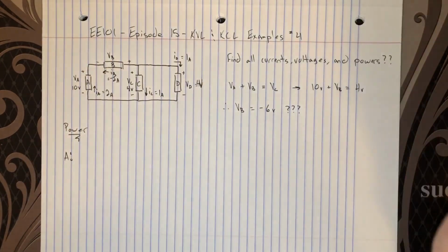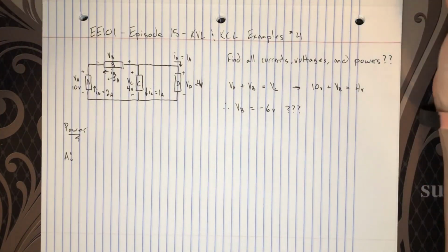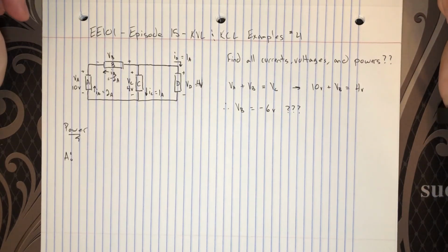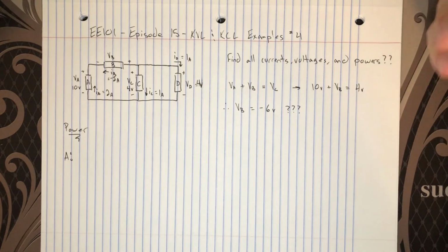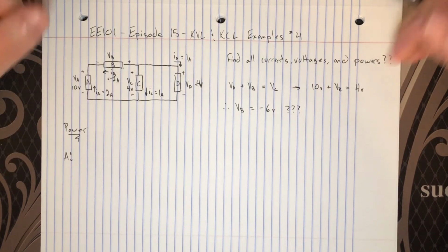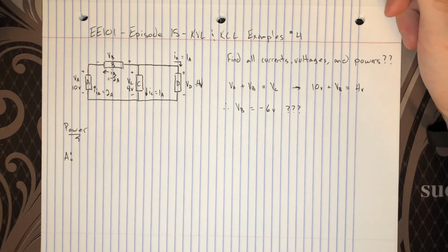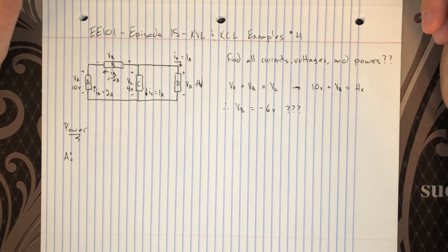And that just all has to do with our convention for voltage and current reference polarities and our convention for counting power, because we want it to turn out that passive elements have positive power, so a positive consumption in our calculations. Then it'll turn out that sources have negative power relative to our calculations.